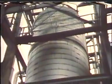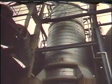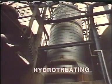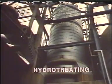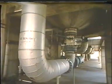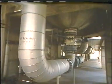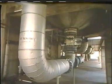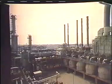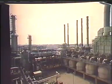The feed is usually given some type of pre-treatment prior to entering the reformer. In most refineries, this means sending the naphtha through a process called hydrotreating or desulfurization. Hydrotreating removes contaminants in the feed, such as sulfur, lead, arsenic, and nitrogen. These impurities must be taken out of the feed, or they will be deposited on the reforming catalyst and damage it. When the naphtha is free of contaminants, it is ready to be reformed.